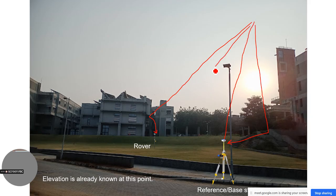Multipath error can be different for both. It is not the same for reference and rover, so that error will be different for both, and that's why we cannot remove multipath using DGPS. Similarly, the error coming from the receiver clock: one clock is in the rover, one clock is in the base station, so both have different errors. That's why receiver clock error also we cannot resolve using DGPS.